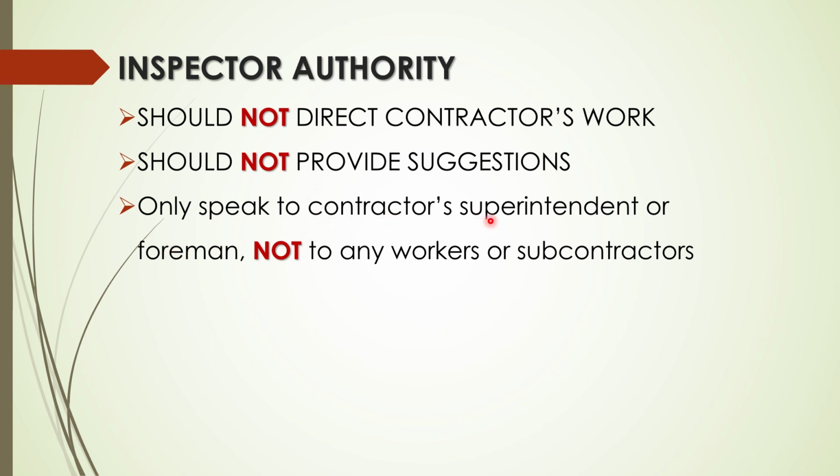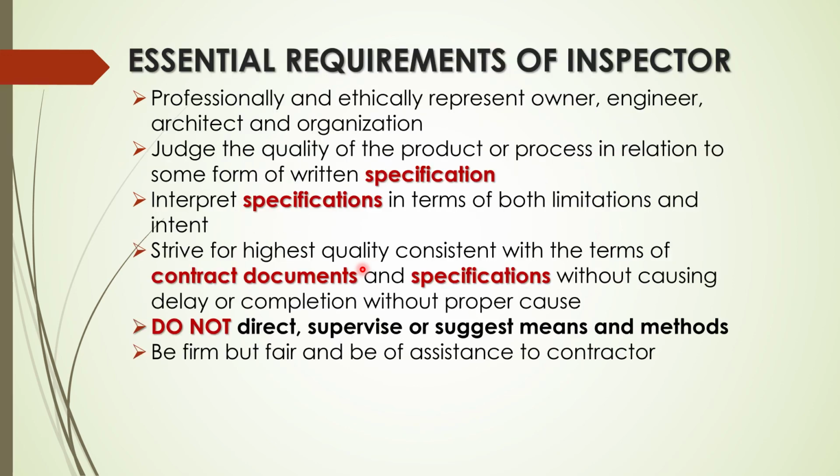Only speak to the contractor superintendent or foreman, not any workers or subcontractors. Especially if something's wrong, if a test fails, make sure you follow the chain of command. Typically, they don't like you talking to the workers, because as soon as you direct the work, the superintendent gets mad at you. So just be careful who you talk to. Follow the chain of command.